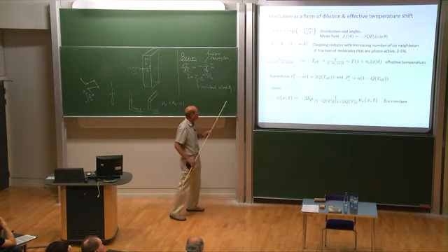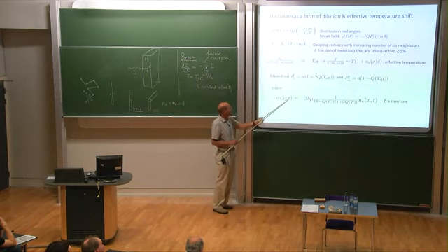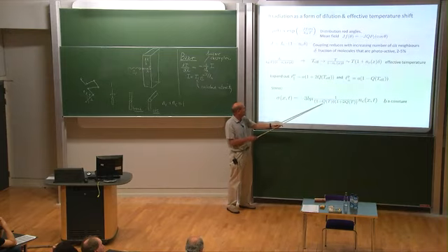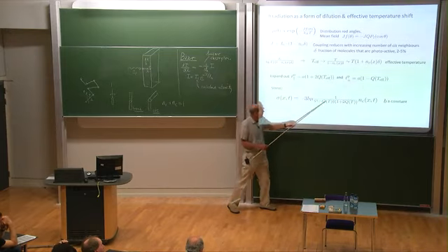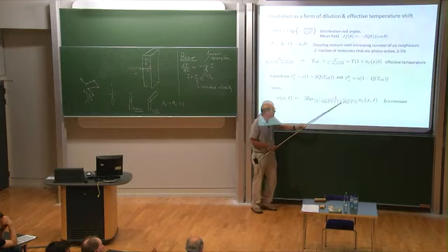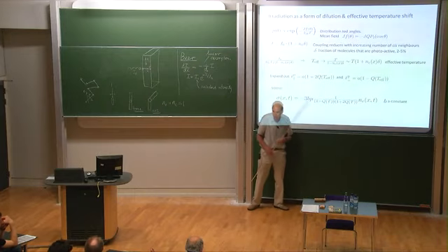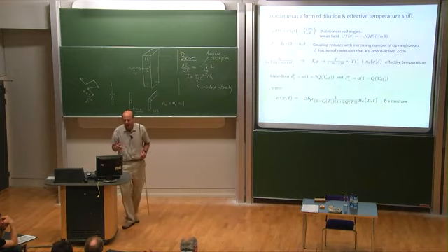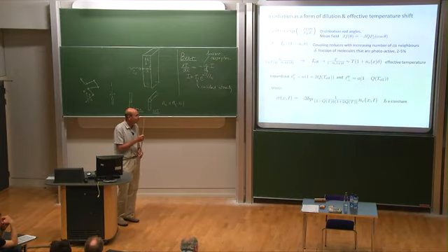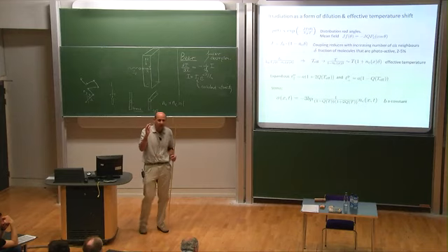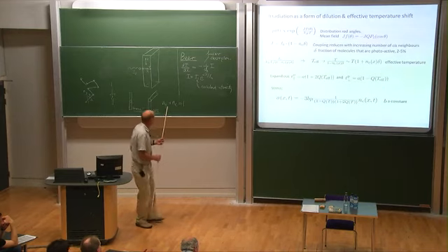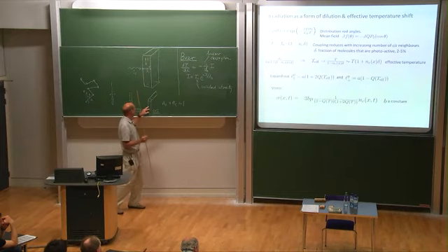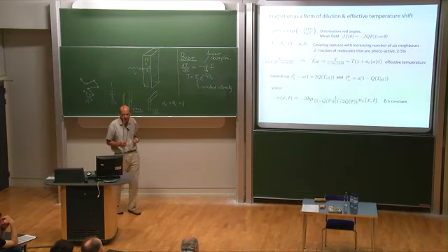So I can say that the stress due to the change of the order parameter is actually this constant out the front times the cis concentration of dye molecules. So it's a powerful result in some sense, because it says I can relate the mechanical properties, the stress, just to the change in the relative population of bent to straight guests.